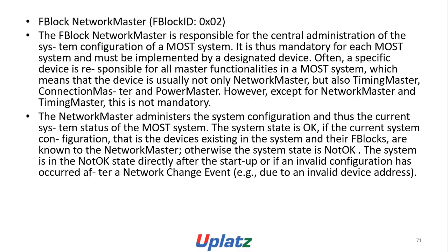FBlock Network Master, FBlock ID 0x02. The FBlock Network Master is responsible for the central administration of the system configuration of the MOST system. It is thus mandatory for each MOST system and must be implemented by the designated device. Often a specific device is responsible for all master functionalities in the MOST system, which means that the device is usually not only network master, but also timing master, connection master, and power master. However, except for the network master and timing master, this is not mandatory.